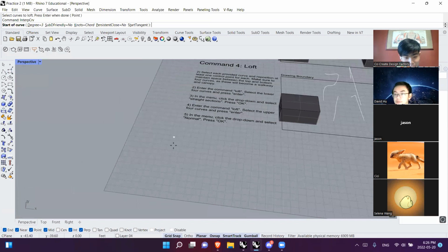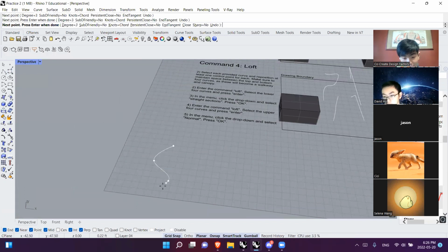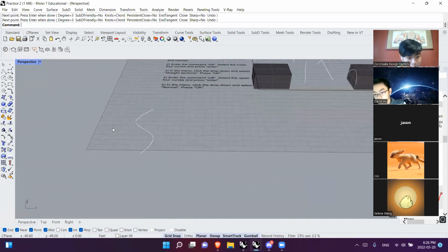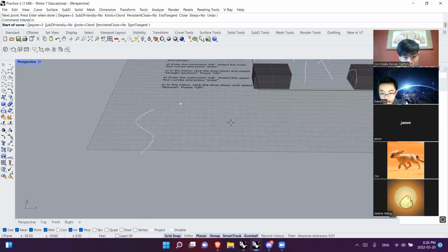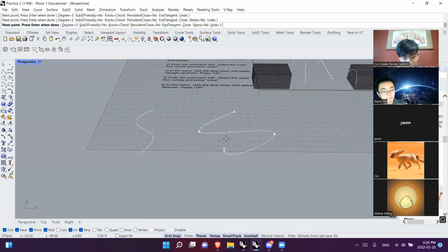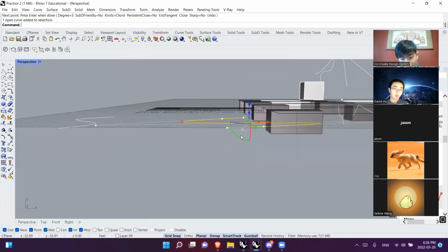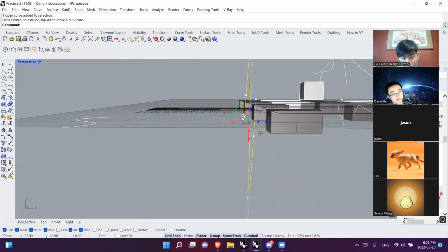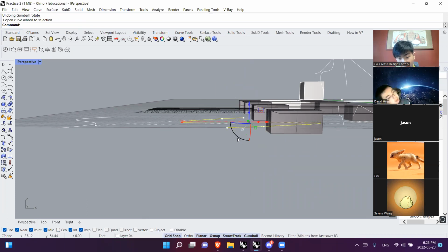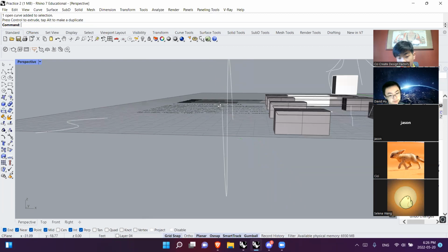because I guess maybe it's an old template that I made. Let's say I have this one here, and I have another one, which makes it a little different, looks like that. So kind of 2 S's here. And if you see this arc here, you can actually drag it to rotate your curve. Then if I want it to rotate 90 degrees, I can hold shift. But if I want it exact 90 degrees, I can hold shift. So that's 180, that's 90 degrees like that.